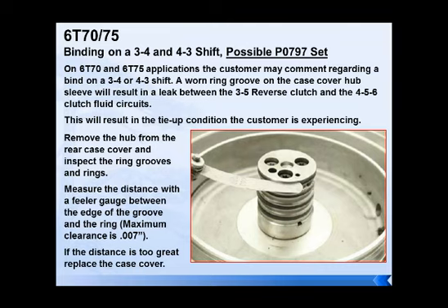Now, if you buy the hub from GM, you buy the whole rear cover. So if you want to go that route, you can. If you buy the hub from Ford, because remember the 6F50 is basically the brother of the 6T70, if you went to Ford and bought the 6F50, you can buy that hub separately. If you notice, that hub is bolted in. So again, either way that you want to replace it is fine with us. Just make sure you check this to be certain that you're not going to have a problem causing you a bind-up condition after this thing gets some mileage on it after you turn it back to the customer.